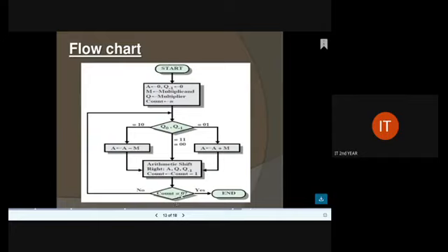If count value is not equal to 0, then it will start from scratch itself, that is Q naught, Q minus 1 value is equal to 1 0, and it will move on to A tends to A minus M, or if Q naught Q minus 1 value is equal to 0 1, then A tends to A plus M. Likewise it will be going on.